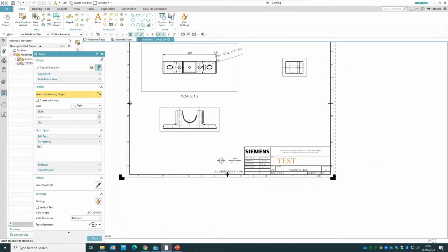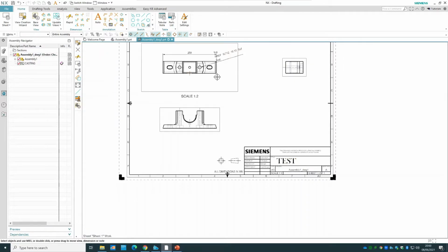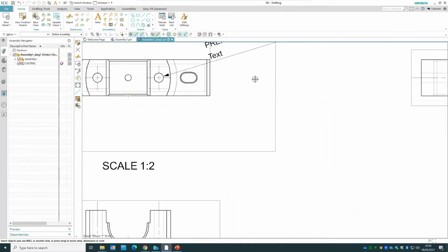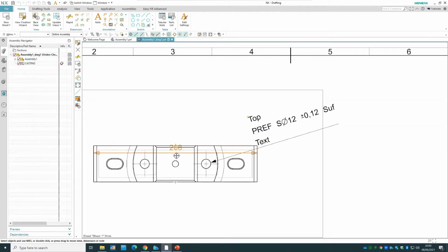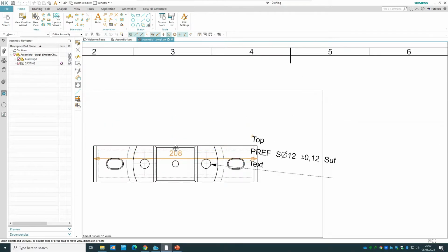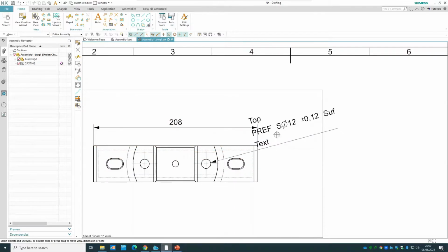Something is really important for you. You need to make sure the main goal of the 2D drawing, it should be really easy to read. So whenever you put these dimensions, make sure they don't block each other, for instance. That's why this dimension is not good. What I recommend is to bring these out.